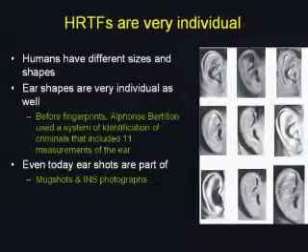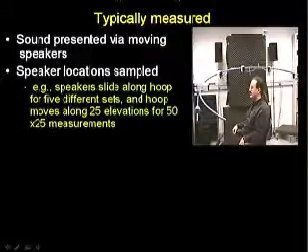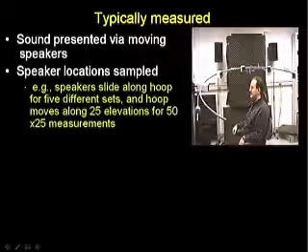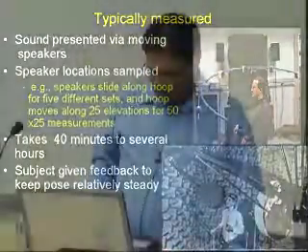And if I want to reproduce virtual reality and give you very stable source locations in audio presentation over headphones, I need to know this transfer function for every individual. Every individual's ear shapes are different, and so the transfer function is different for every person. Measuring this transfer function used to be a relatively tedious affair. You would take a speaker, play a chirp from one location, then play a chirp from another location, and so on. You would do this over 2 hours and maybe 1,000 directions, and that would give you the head-related transfer function.